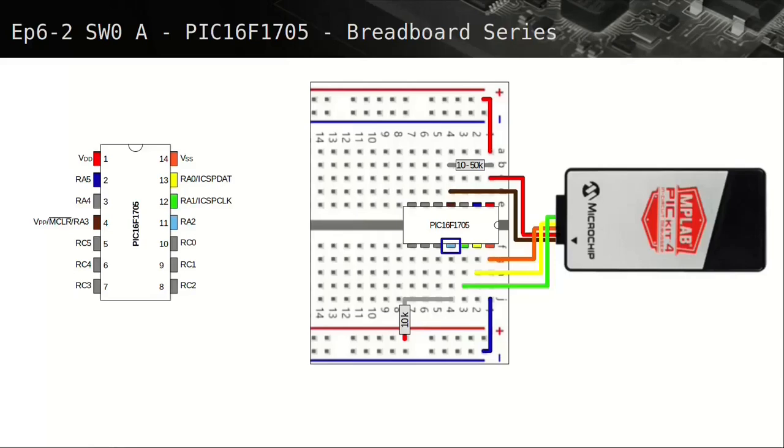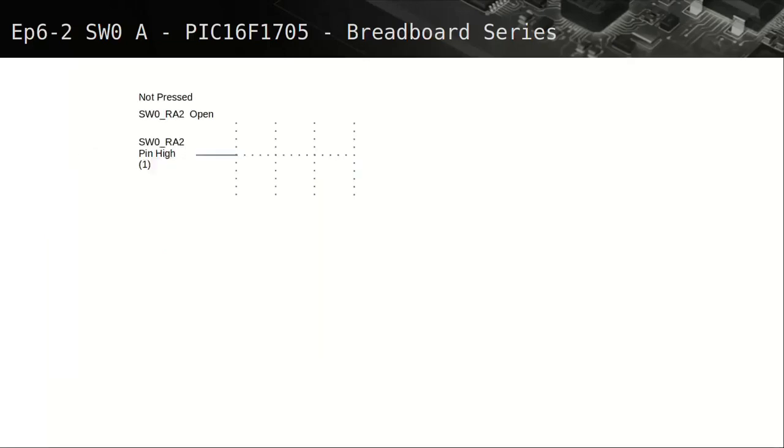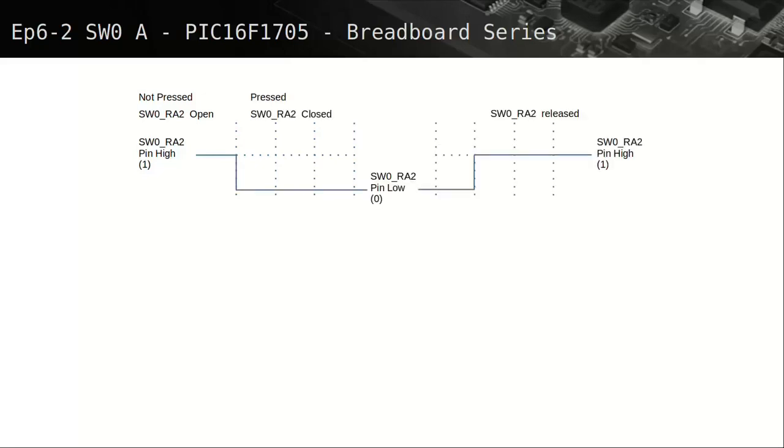1 when the switch is not pressed. One of the switch's normally open contact pins is connected to ground and the other pin to RA2. When the switch is pressed, the contact closes and pulls the pin voltage low for a sinking circuit, or active low. A person would expect this type of switch's contact to close and open immediately, producing a clean transition from open to closed or closed to open.